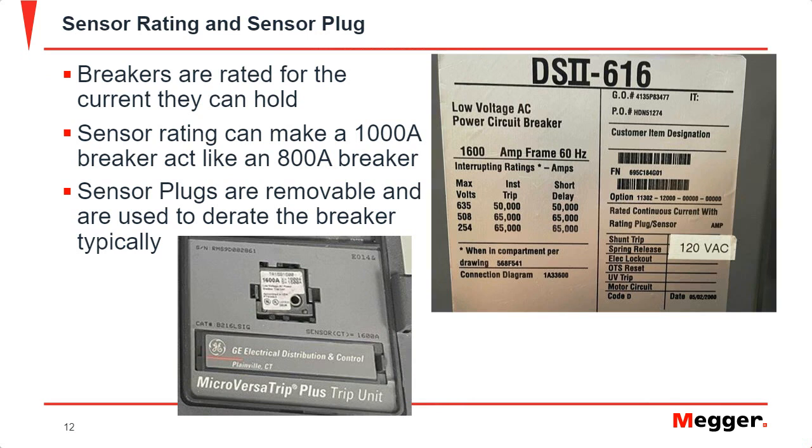Now, when testing breakers, you typically test to whatever the rating of the breaker is. Seen here in the picture, you'll see a 1600 amp frame size breaker. Now, breakers can be derated, and when you derate a breaker, typically you'll put in a sensor plug. Sensor plugs are removable, and they're used to, again, derate the breaker. You can always derate a breaker, but you can never make a breaker higher than what its frame rating is.